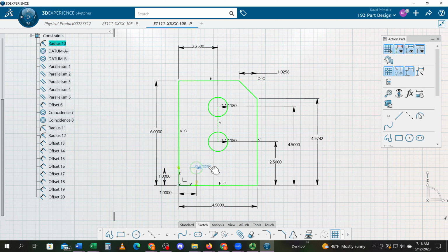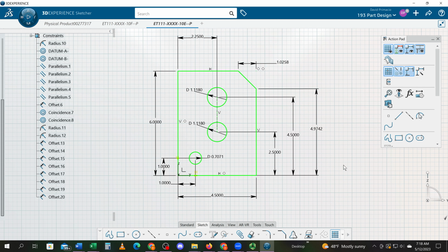And I like to move the dimensions off just a hair. Now on a drawing, I couldn't do this. I would have to move it off the part like this on a drawing, but on a sketch, I can leave this here like this. This is fine to do. Again, on a drawing, yes. Now here's the problem here too. I have to move this way out here so I can grab this and then move it around over here. Okay. That is a perfectly constrained profile.